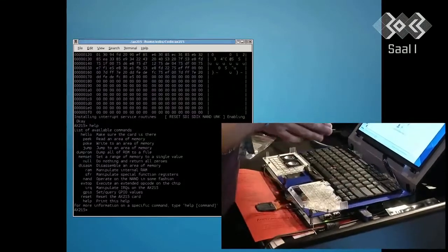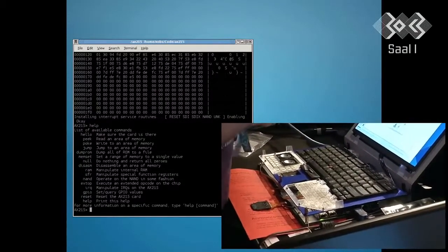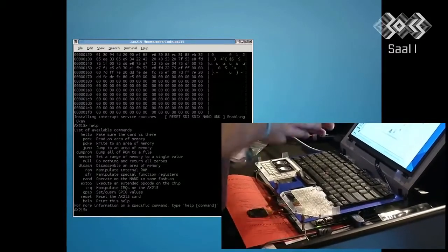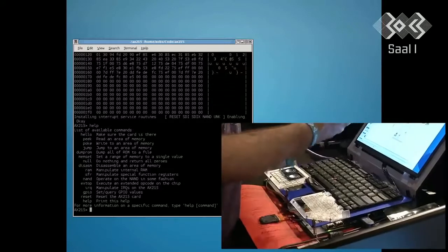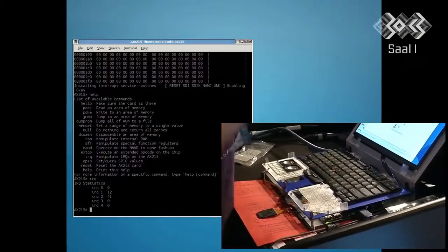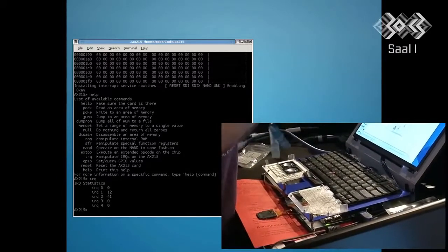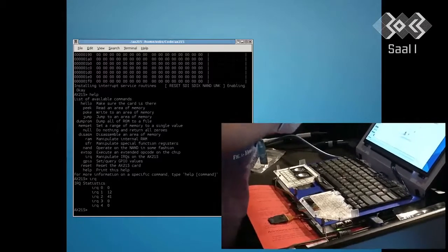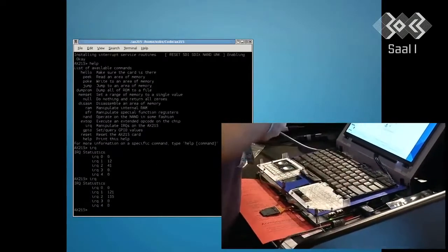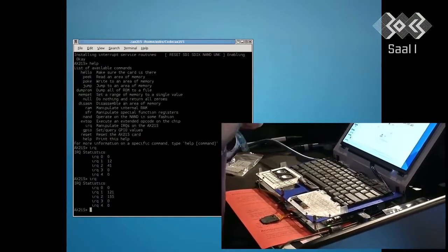We've got a few commands you could run. There's hello, peek, poke, the usual ones. Jump, so you can load code in with peek or poke and actually jump to it. There's IRQ, which is what we use to figure out what the IRQ table does. This card has 5 IRQs, 0 through 4. IRQ 0 we know from 8051 is reset. If you look at this, IRQs 1 and 2 are not 0. And if we query the IRQs again, they keep going up. These are counters for the number of times the IRQs fire, just to clarify.